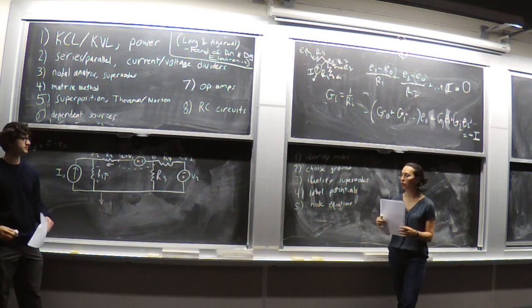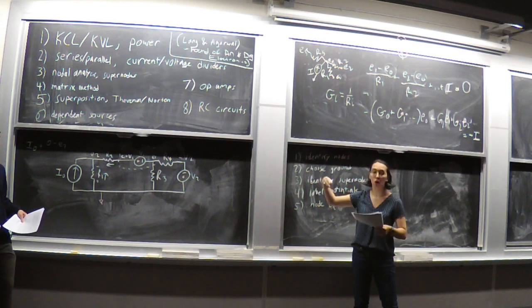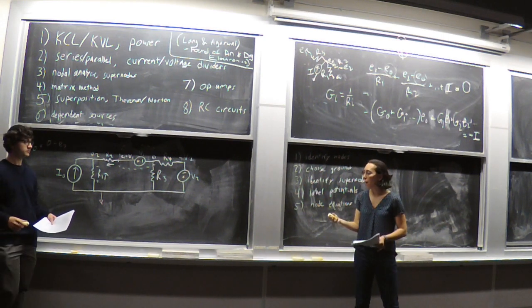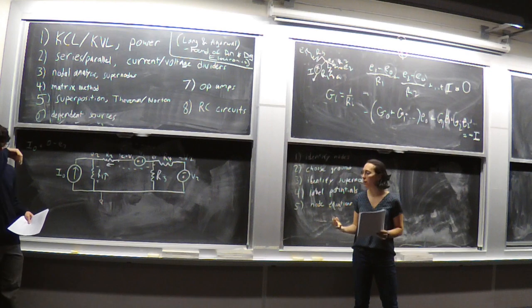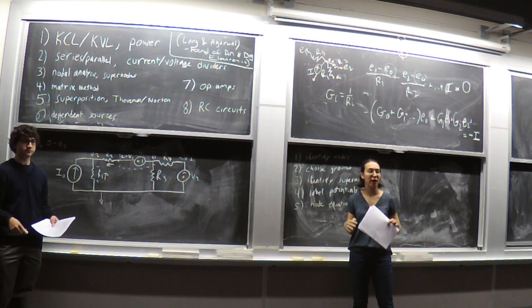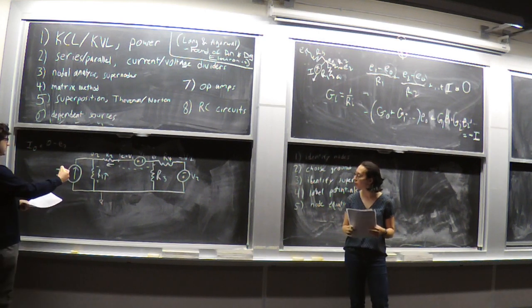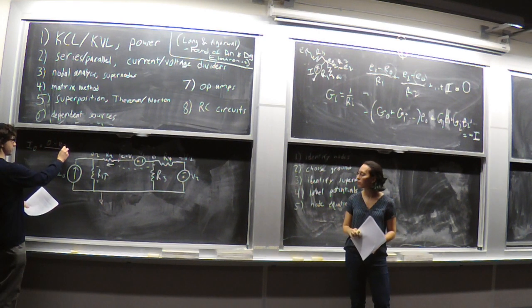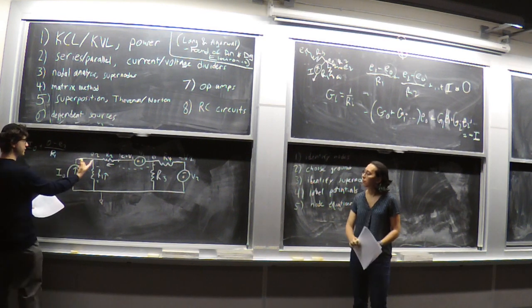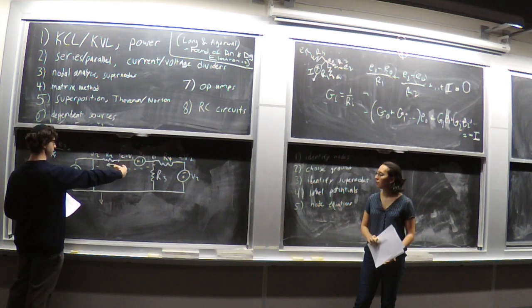So you very well could have decided you wanted to sum up the node equation as having all currents going out of the node. And that would also be fine, but just make sure you're consistent. So pick a direction and make sure you stick with it. So either everything goes in, or everything goes out. And one trick for doing that we'll see in a second. So this is the voltage drop across R1, and then we have to divide by R1 to get the current through R1.